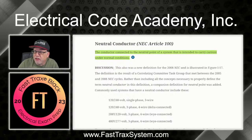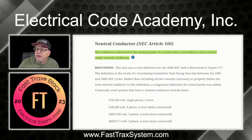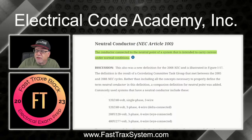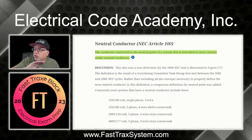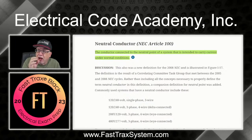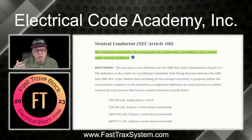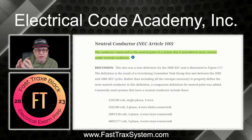Important. It says, this also was a new definition. Neutral conductor was a new definition in 2008, okay? And as is illustrated in Figure 1-17, which we're going to look at, it shows the neutral point, which was also added to the code in 2008, and how a neutral conductor is derived. I think that if you see that, it'll start to hammer home the importance of all of those safety issues of, again, not connecting equipment grounds to neutrals downstream, and all those things will start to come together, and we all become better electricians over it.